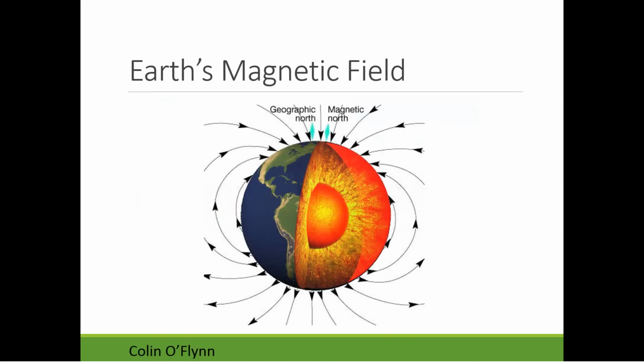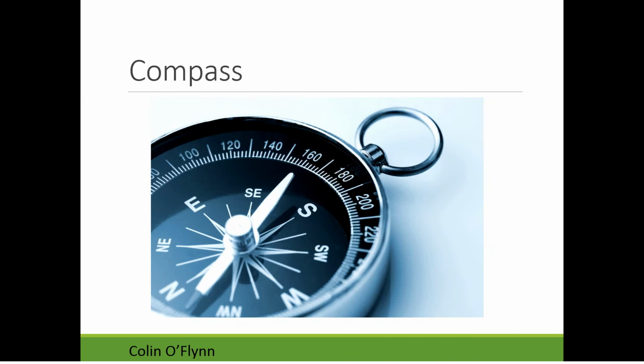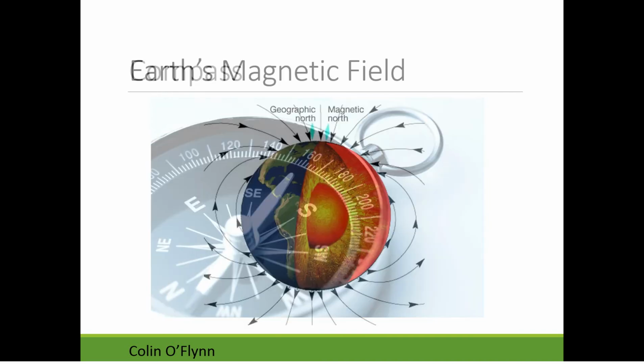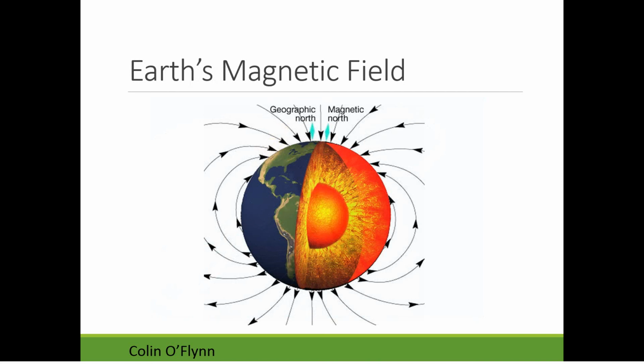And the same thing for when we're detecting the Earth's magnetic field. This is where the magnetometer comes in, which you also have in your kit, as there's just one chip that does all 3 of these. So this is detecting, like a compass, the Earth's magnetic field. We have 3 axes because the Earth's magnetic field is not perfectly parallel to the surface, but instead comes in at an angle.